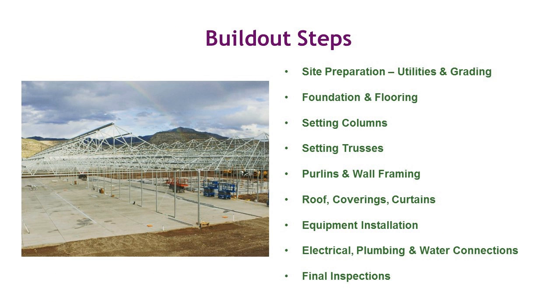We'll summarize it here, and it doesn't necessarily always go in this order, but it pretty much adheres to this pattern from what we've seen. So the very first thing you would want is site preparation, and oftentimes that means, for folks in rural locations, bringing in utilities. If you already have utilities, that's great. You can put them underground and move them to where the site is and have them out of the way while you're doing your grading work.